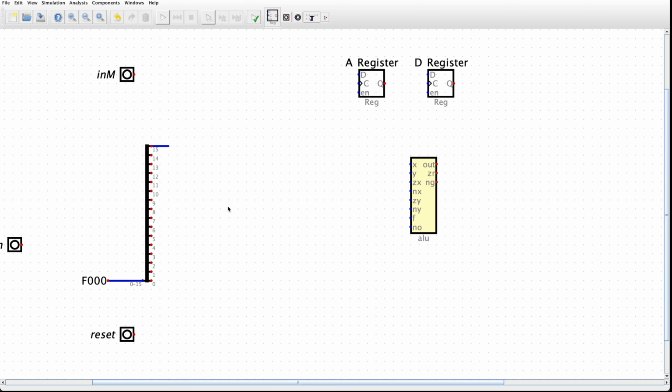So one thing we could do is we could just start drawing wires here and wiring them up. But there's another argument here, which is if we connect these all to nets, then we can have a much neater layout and just pull these control bits out where we need them. And so I'm going to actually do this that way.